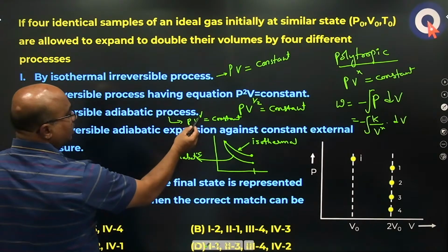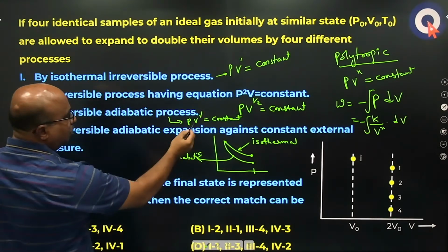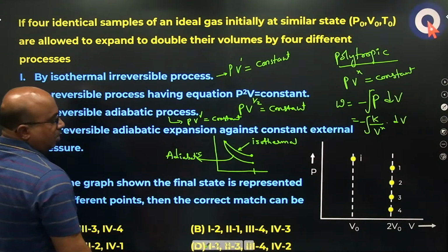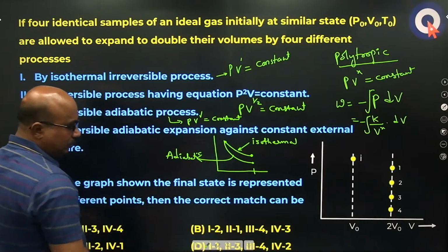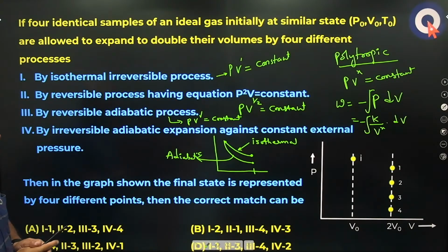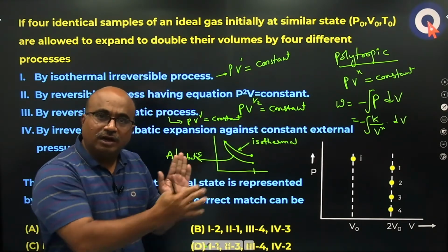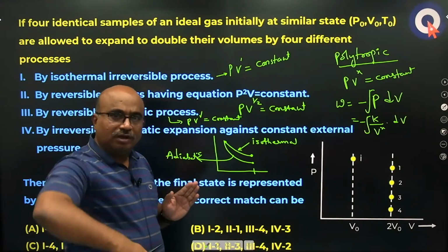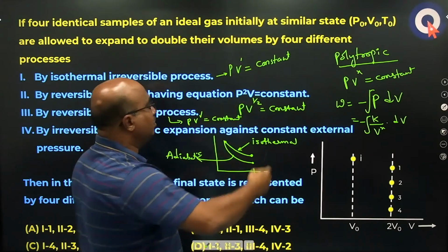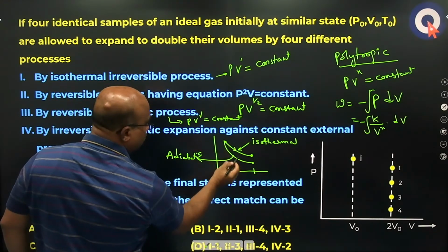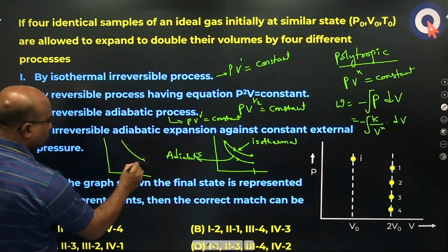So when the gamma values are taken, which are generally greater than 1, here it is V to the power of 1, here it is V to the power of gamma. It means as the gamma value is increasing, the area under the curve will decrease. Here, as the value of X is increasing, the area under the curve will decrease. It becomes steeper. If it is compression, the graphs will be reversed. So from here we are going like this.